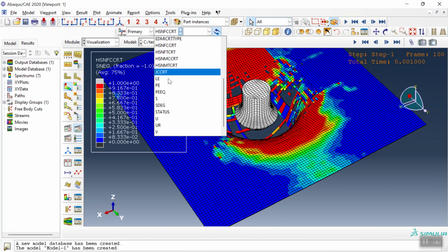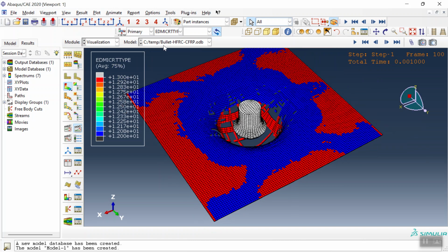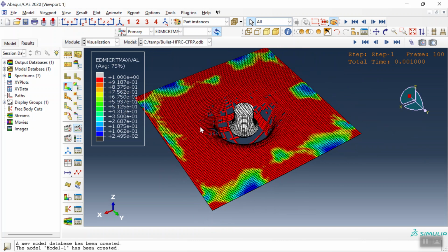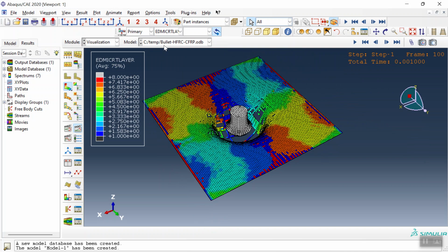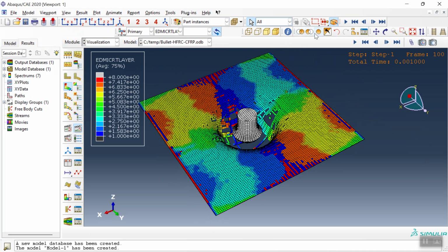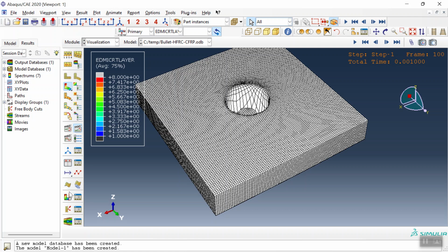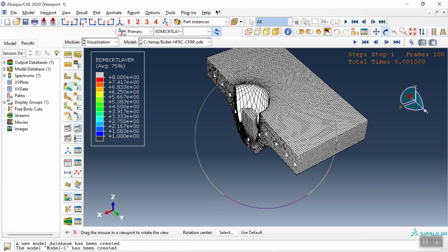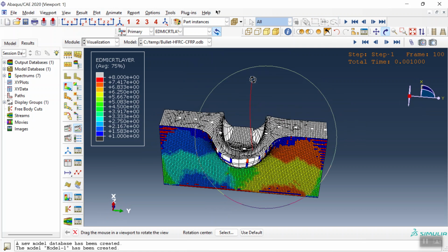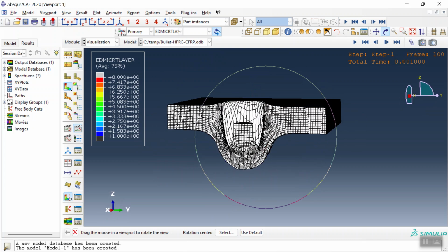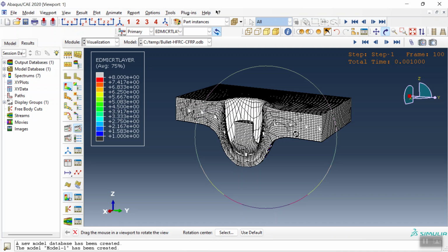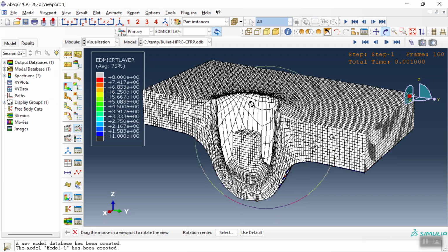Okay, and the other damage criterion from Abaqus for each layer, we can request it for each layer. So this is the model of the high velocity or ballistic impact onto the steel polypropylene hybrid fiber reinforced concrete panel reinforced with CFRP and steel reinforcement.